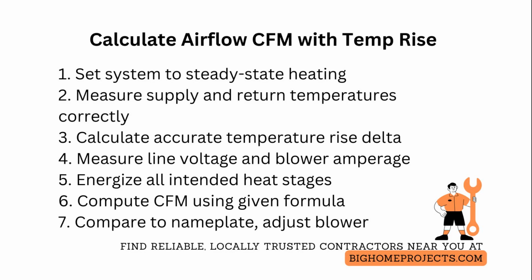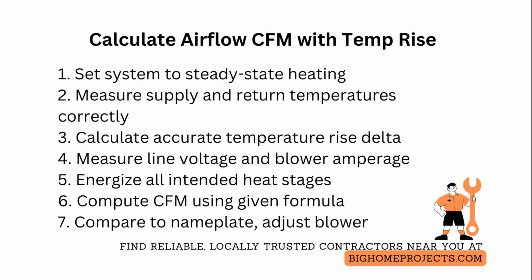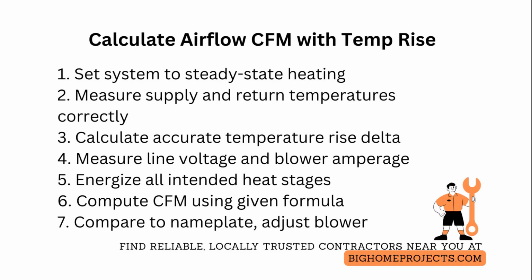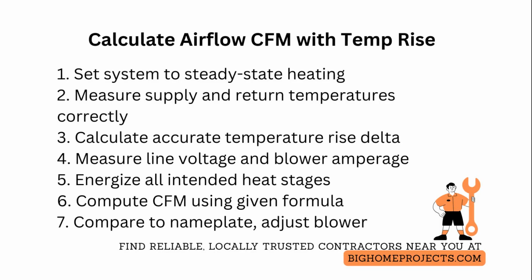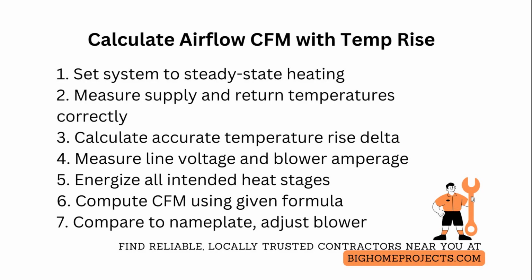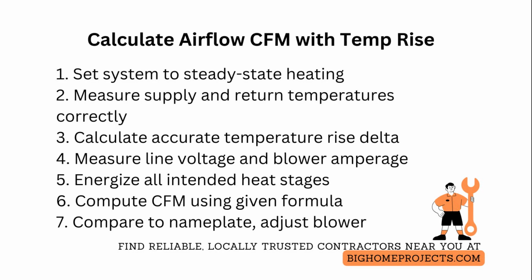Validate the result against nameplate rated airflow for the equipment tonnage or capacity, then tweak blower speed taps or speed percentages and recheck temperature rise until cubic feet per minute aligns with target. Log ambient conditions, filter condition, duct static pressure, and all readings, so the calculation is reproducible and defensible for service records and quality control.